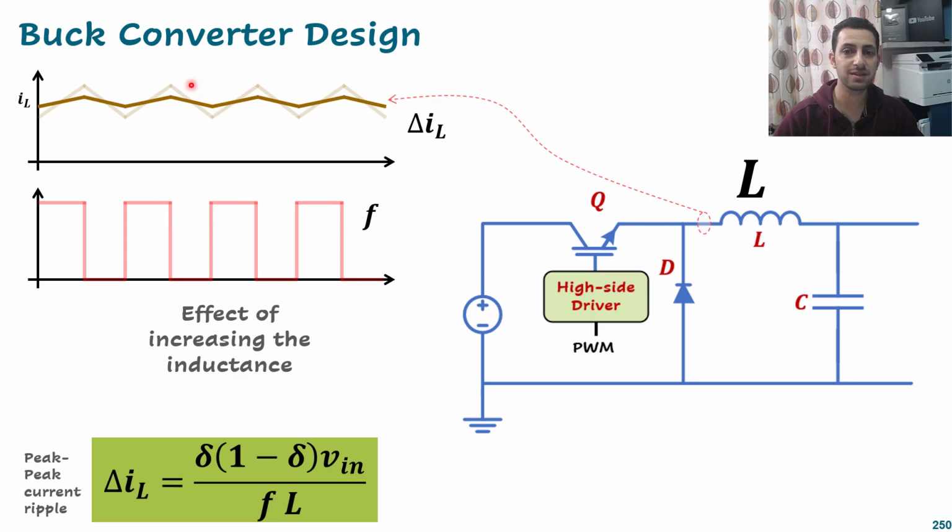This is something that can be considered, but if you want to increase the inductance to decrease your ripple, sometimes you need to pay more cost, because you are increasing the inductance by increasing the size, for example. But maybe you think, why don't I just increase the frequency, because it's software matters. However, the frequency increase is sometimes limited by the speed of the switch, or the speed of the entire circuit, or other considerations.